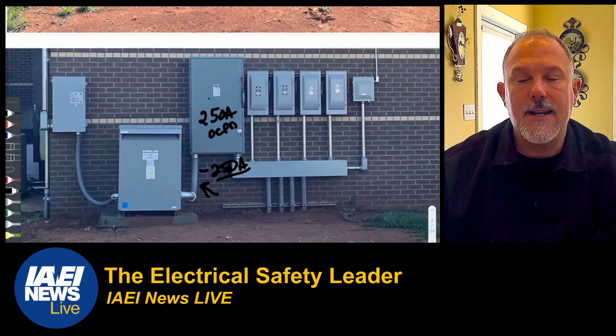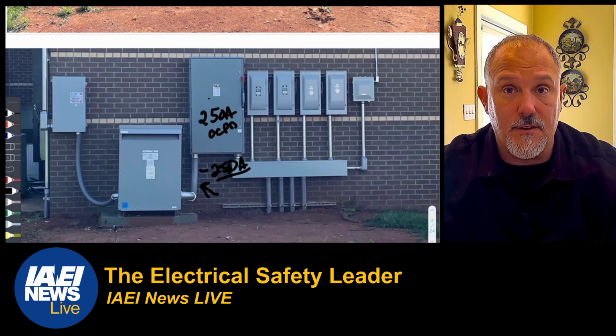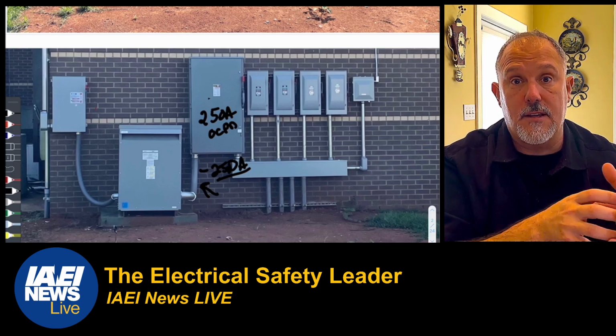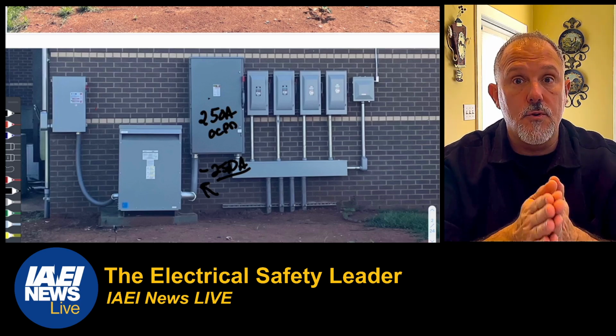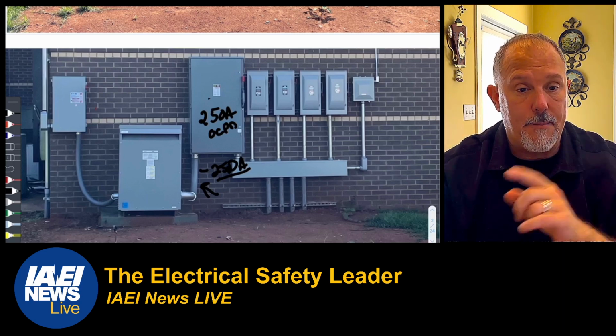So that secondary conductor is not protected. Very similar to service overcurrent protective devices. And we have a lot of rules to protect the service overcurrent protective devices, including the raceway that it's put in, the bonding, etc. You have similar rules for these transformer secondary conductors because it's very similar to that application.